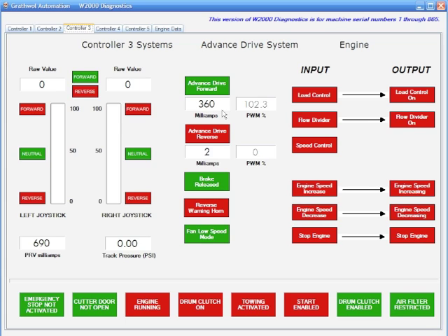They're all over the place. This is what you'll see if you've got smashed wires, a shorted coil, or a shorted plug. The milliamps are going to vary. They're going to be lower than they should be, but your PWM is going to be at full. This is a full output condition. Now I'm going to bring it back to neutral, and we're going to put everything back to normal.